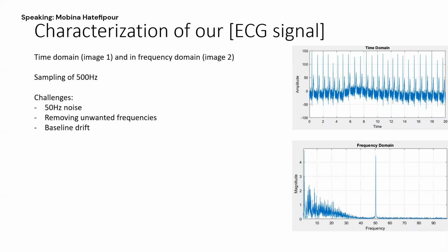As mentioned earlier, the sampling frequency of our signal is 500 Hz. 500 Hz is suitable, for it allows us to catch the quick changes during the period of a heartbeat, and we need to be able to catch the electrical changes to identify our signal. Between 200 to 500 Hz is generally considered optimal for both time and frequency domain. Any lower or any higher frequency would not be acceptable and would not show good results.